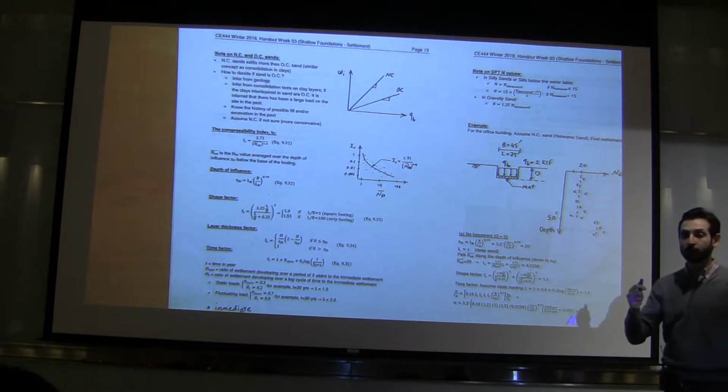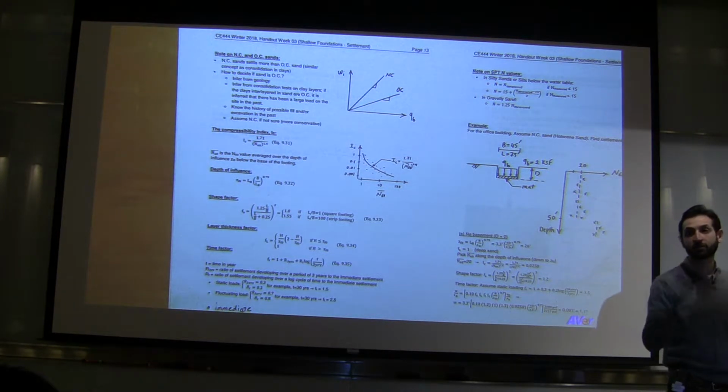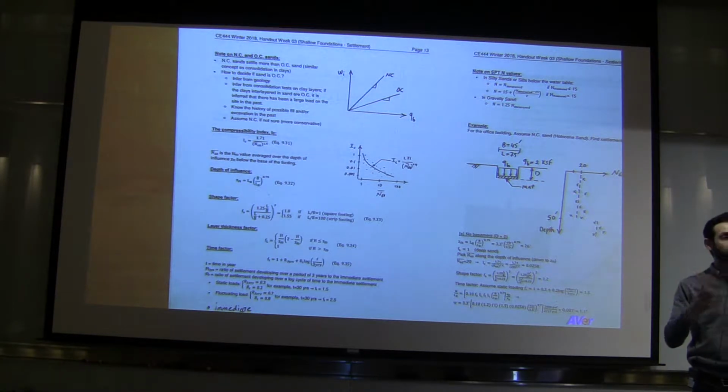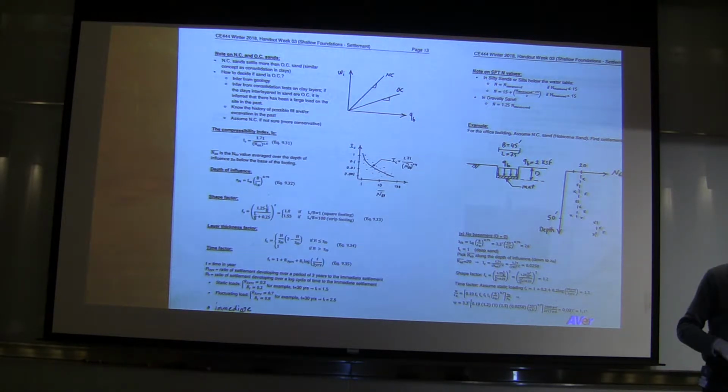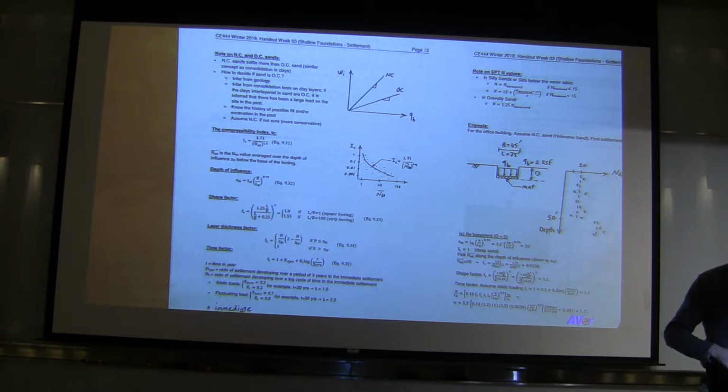The answer is yes. The reason we are doing this is that we can't do the typical consolidation test on sand. It doesn't work. But we can use the data from the layer on top and below that sand layer to know that this sand was subjected to some large areal load in its past. Does that make sense?